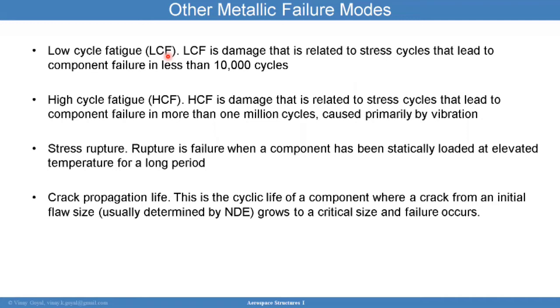Crack propagation life, this is cyclic loading of a component where there's an initial crack in the system. And the initial crack grows over the life of the part to a critical level, and then it propagates unstably.